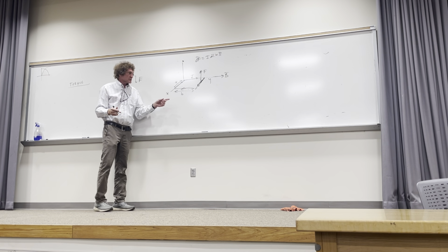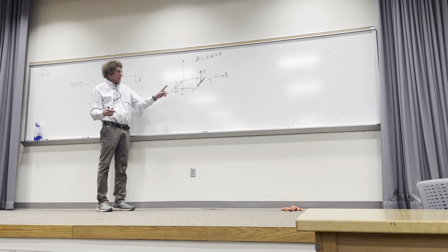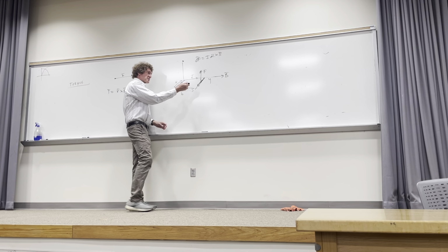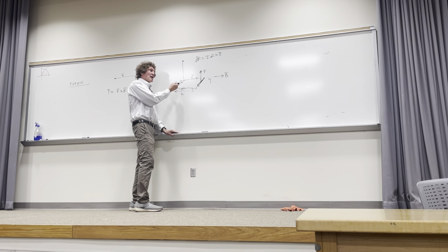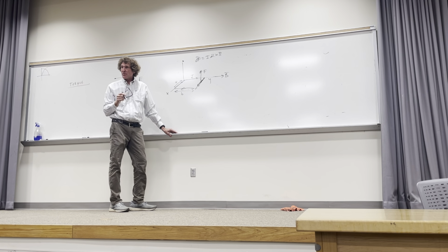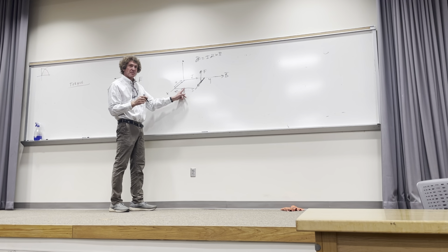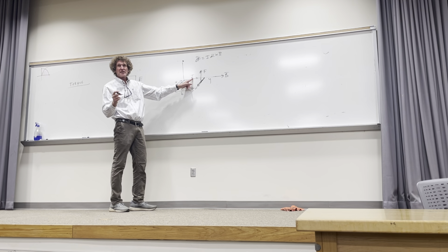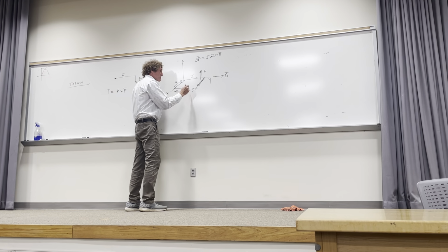Now what about the force on this member? Take a good look at this before you just turn yourself into a pretzel. I've got I dL this way, what direction? Negative AY. Crossed into B, what direction? Positive AY. Is 0. No force. Y'all hear me on that? Whoever said that's right. There's no force there. As a matter of fact, there's no force on this member. Anytime the current is in the same direction as the B field, there is no force. That's one thing you make sure you get. No force there and there.